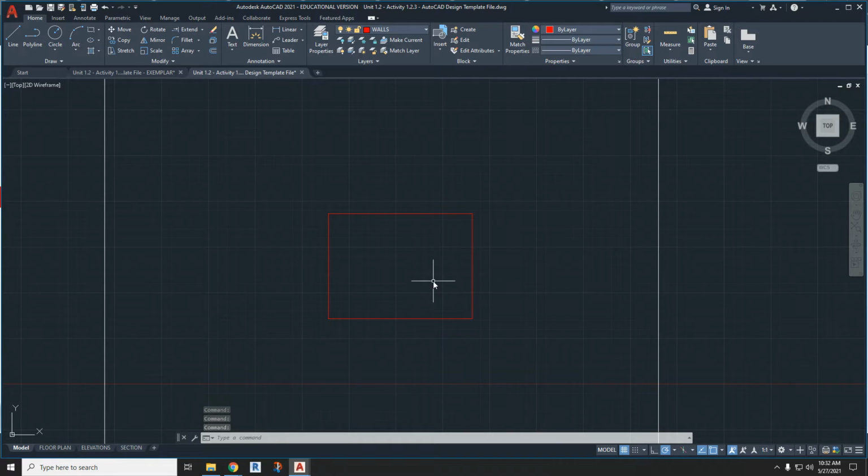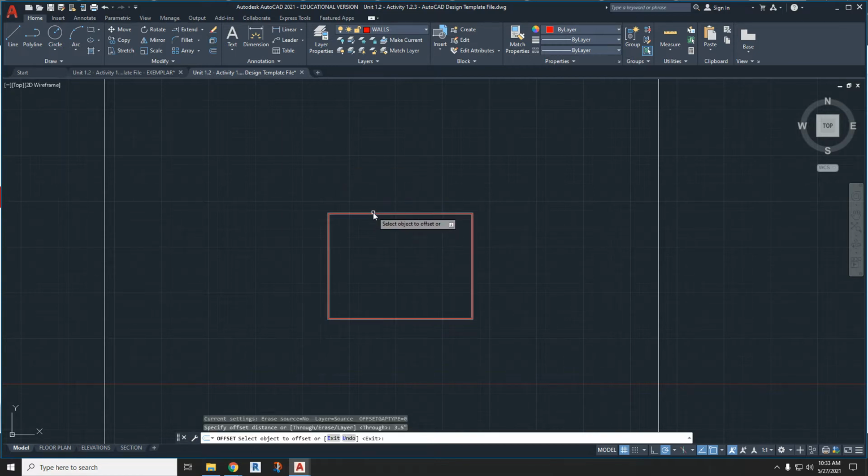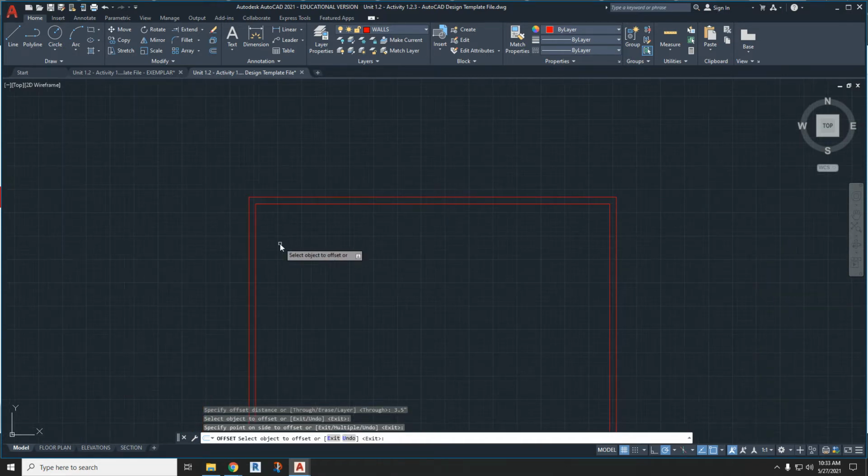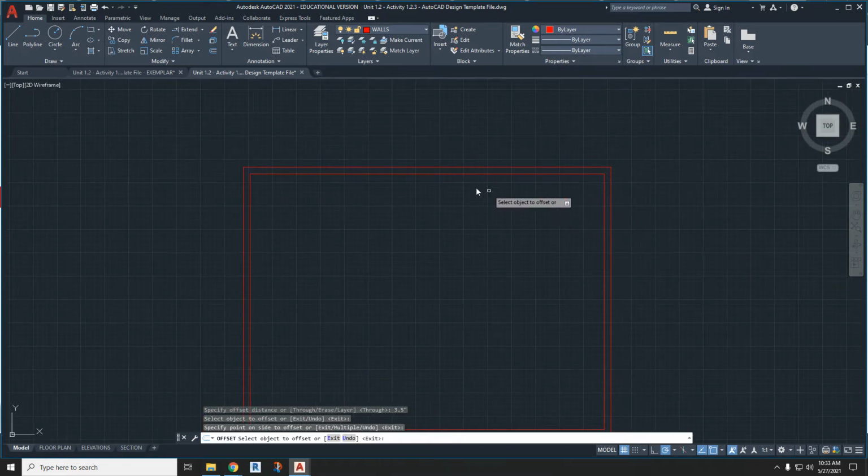So remember the 12 by 16, that's the outer edge of the studs for the wall. And 2 by 4 studs are 3.5 inches thick. So there's a tool here for offset. So if you want to offset, you can offset through 3.5 inches. And then I can click on this and make sure it goes inside, not outside, inside. All right. And that's the inside of the studs. And then hit escape, hit enter just to recall the distance.